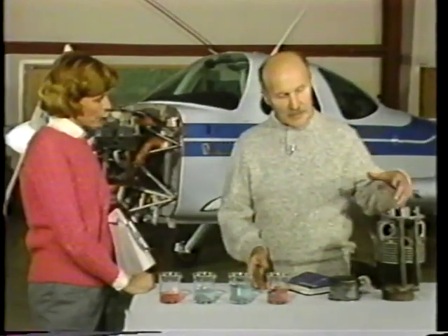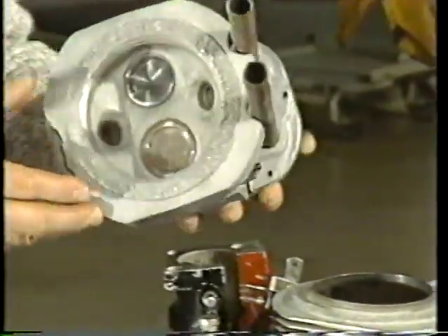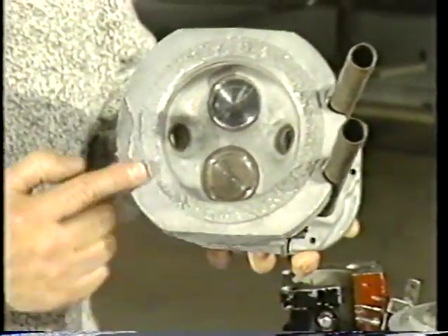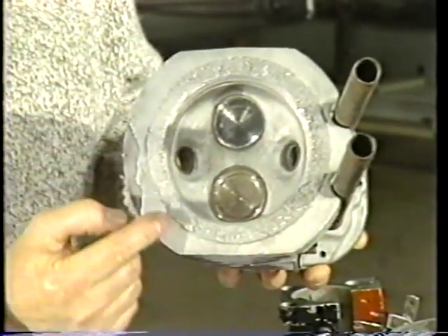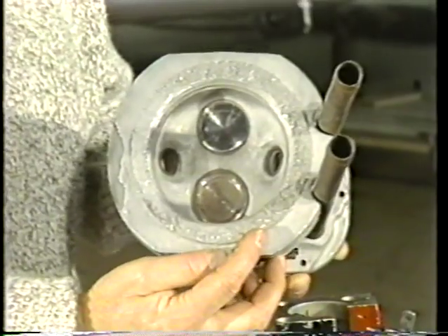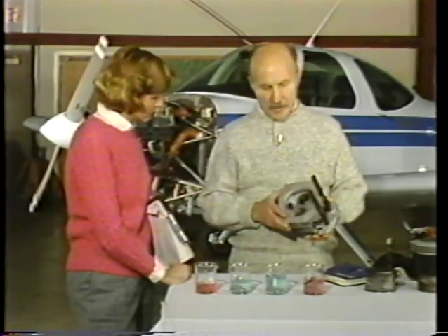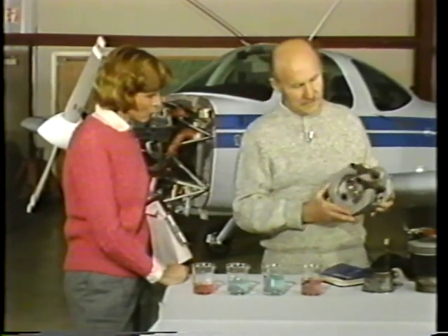If we have a severe case of this, we may even have a cylinder failure, such as this one, where the pressure was built up so much that it actually fractured the cylinder head. The cylinder head would then fail, and we'd have probably a total engine failure. This was likely to occur, say, on takeoff, when it's very critical for the pilot to have his engine. And it gets suddenly very quiet.